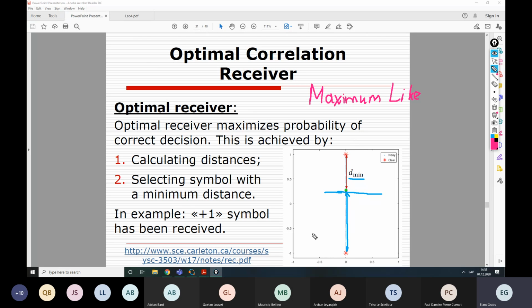Of course, there is a probability that actually we transmitted this point and the noise was that strong that it actually changed here, and then if we use this logic, we would receive signal incorrectly. And that's actually how errors are happening in the receiver, because that's quite possible. However, the probability of such event is lower than we will have it belonging to this point originally, likelihood.